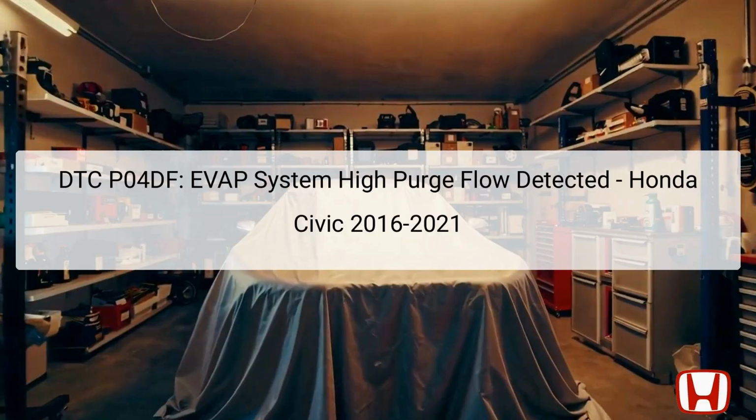The presentation focuses on DTC P04DF, which indicates a high purge flow in the EVAP system of the Honda Civic models from 2016 to 2021. This trouble code is specifically related to the vehicle's evaporative emission control system, indicating that the EVAP system is experiencing issues. High purge flow detected can lead to increased emissions and reduced engine performance.